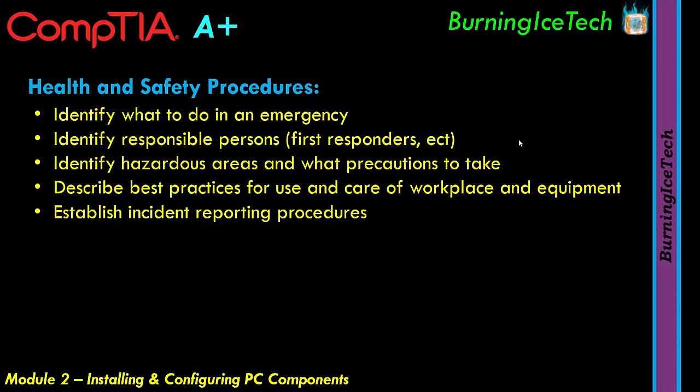It could be something like a printer. A lot of printers, especially if you go look at laser printers, they've got high voltage. And when you open that printer to go and service it in some sort of manner, that is considered working in an area. So what precautions should you take in an area like that? Well, obviously, if possible, turn off the printer. Preferably unplug it just to be on the safe side.